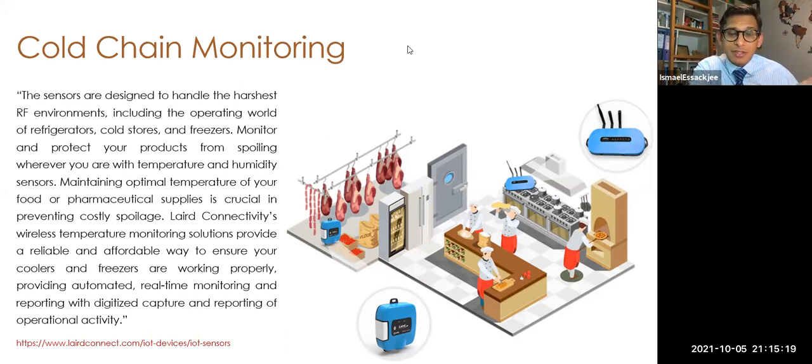At times, if it is working in a cold environment, the mechanical system may freeze. So be careful. If you have oil in the mechanical system and it is too cold, the oil is going to become solid, so it's going to block the actuator from working. So you will need to look for another type, maybe a pneumatic system and so on.